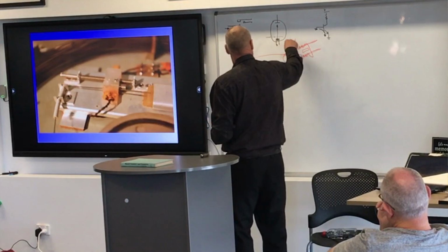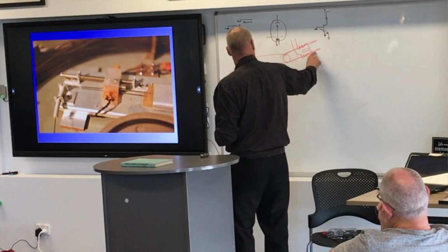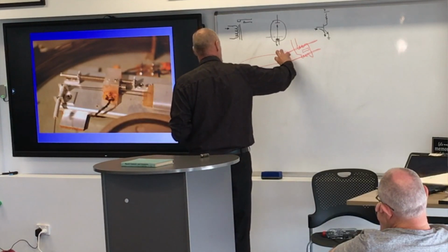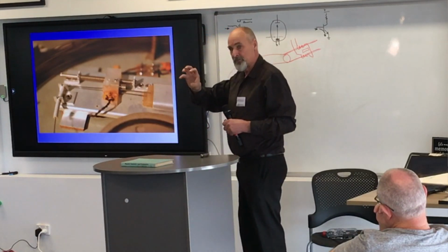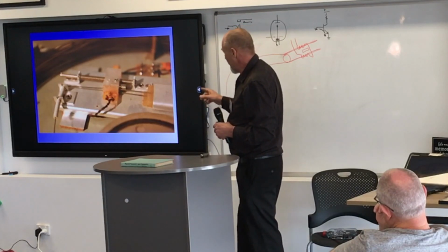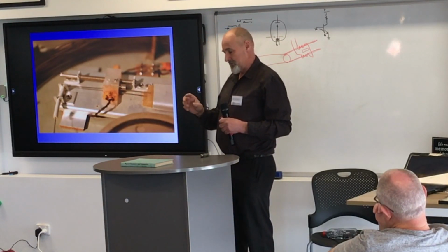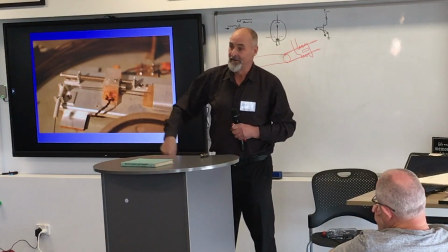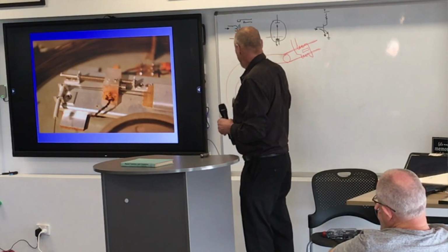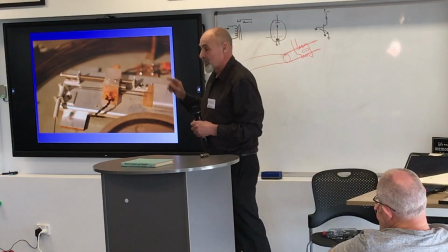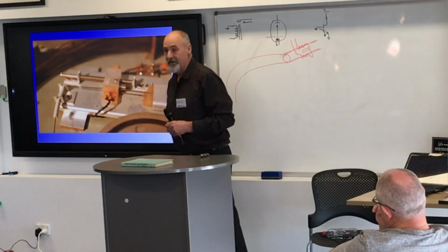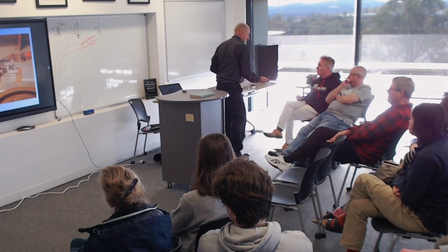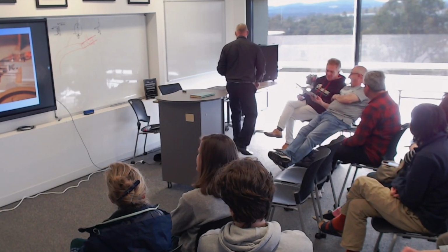So by putting a pulse on here, we can cause this one to relax and this one to go tight, and the delay line goes beep, little torsional shock wave. So the actual delay line is a mechanical torsional shock wave that spirals down the wire and then pops out the other end, and the Villari effect causes a pulse to be detected by the receiver. So, yeah, pass that around. Here's one I prepared earlier.